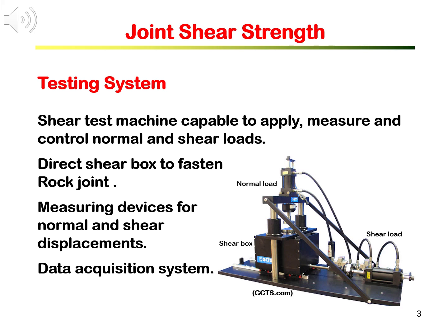The test specimen is assembled in a direct shear box. The shear box has upper and lower halves to fix the upper and the lower half of the joint. While one half is sliding against the other half, it brings the joint to shear along the joint plane.